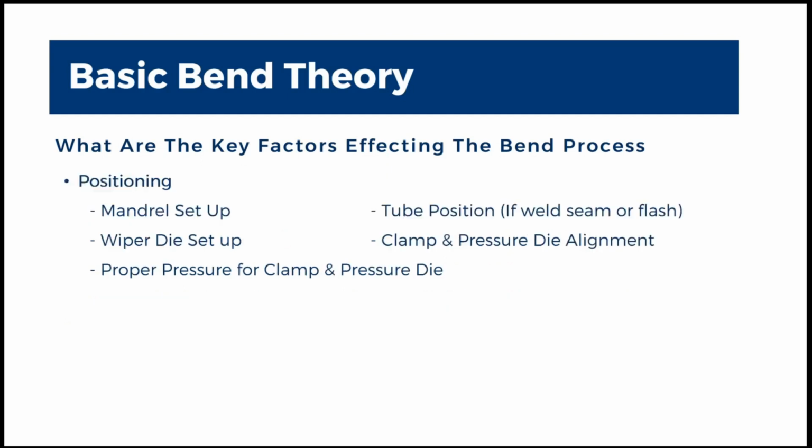The main components affecting positioning are mandrel setup, wiper die setup, proper pressure for clamps and pressure die, tube position if you have a weld seam or flash, clamp and pressure alignment.